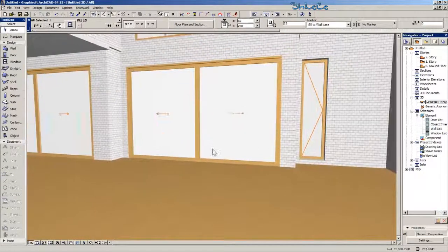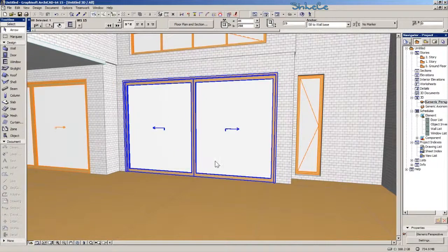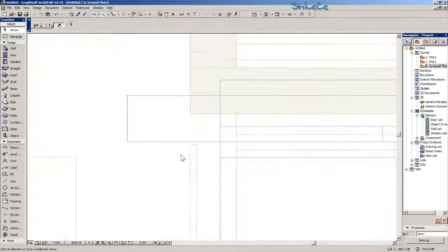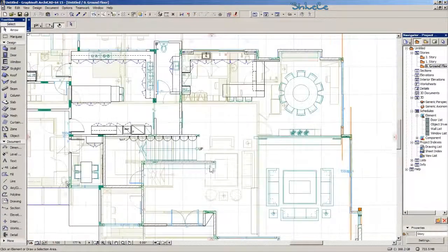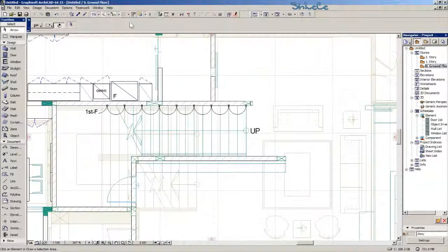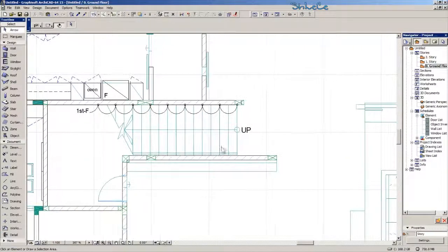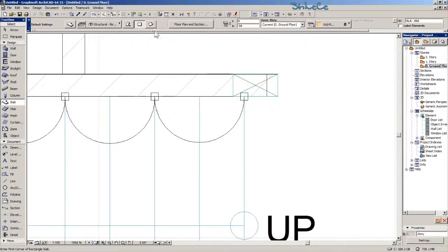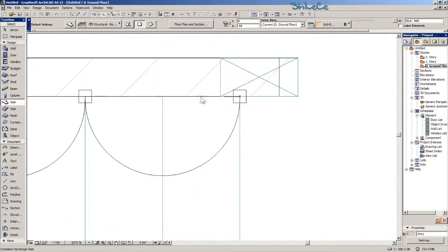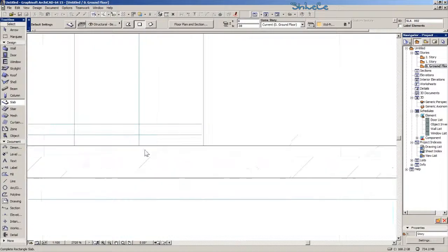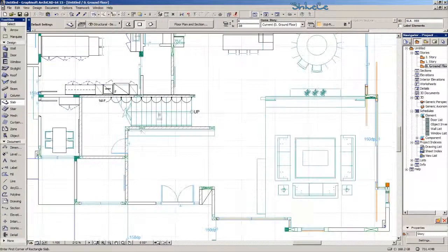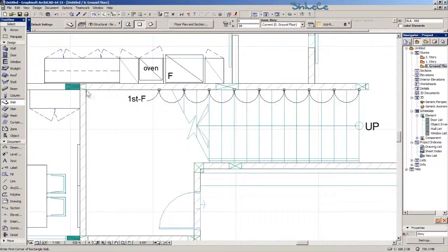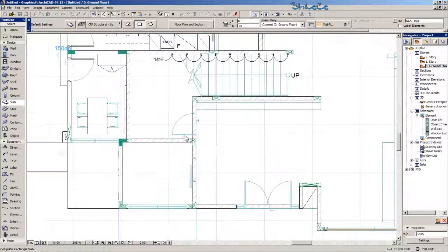The last remaining part is the stair. Let me disable the tracing. Okay, so I'm gonna select the slab tool and make sure that it is set to rectangle mode and just draw one in here. Fine. Then I'm gonna select and draw a rectangle this size.